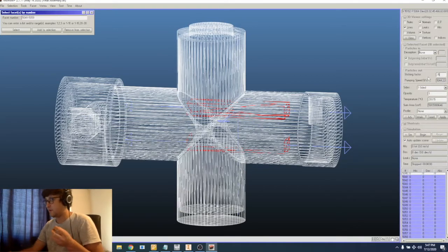That's fine. If I wanted to be more precise, I could put 12 or 11. Now for all of these pumps, it's about a quarter of the specified manufacturer pump speed, which is probably a good estimation for ultra high vacuum.